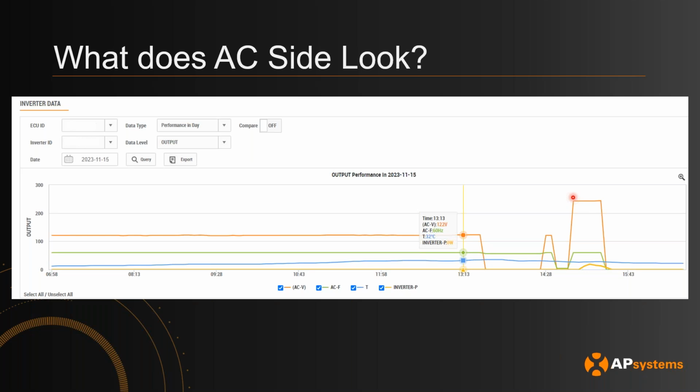Similarly, if you notice that there are a lot of microinverters that had 0 volts on the AC, it's going to be good to check whether there's a breaker issue, a home run issue, or a wiring issue on the AC for that particular branch. That can be another thing that'll be helpful to identify where to look to debug systems.